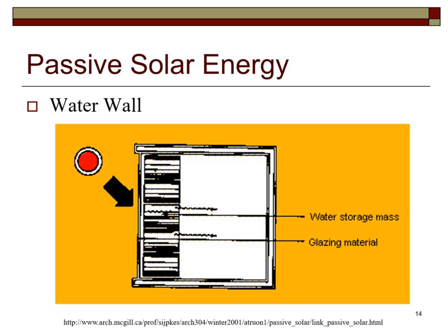The convection currents in water rapidly transfer the solar heat from the collection surface to the rest of the volume of water and thence the rooms. Consequently, the water walls lose less heat to the outdoors and are more efficient collectors of solar energy than concrete walls.